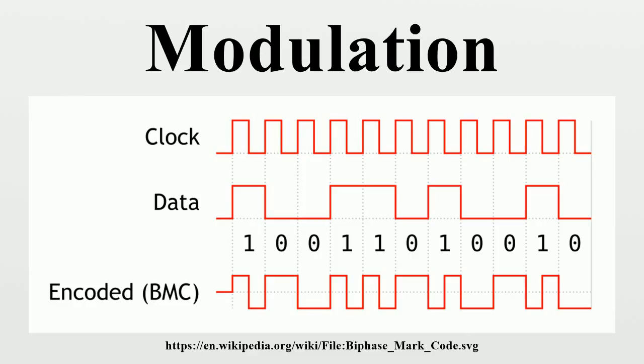Pulse modulation methods. Pulse modulation schemes aim at transferring a narrowband analog signal over an analog baseband channel as a two-level signal by modulating a pulse wave. Some pulse modulation schemes also allow the narrowband analog signal to be transferred as a digital signal with a fixed bit rate, which can be transferred over an underlying digital transmission system, for example, some line code. These are not modulation schemes in the conventional sense since they are not channel coding schemes, but should be considered as source coding schemes, and in some cases analog-to-digital conversion techniques.